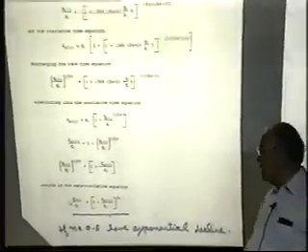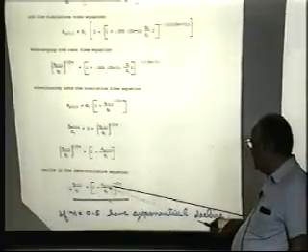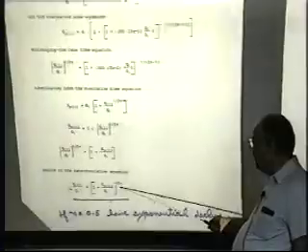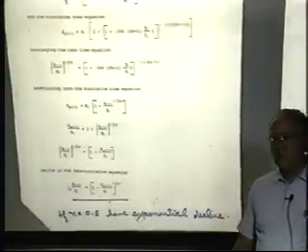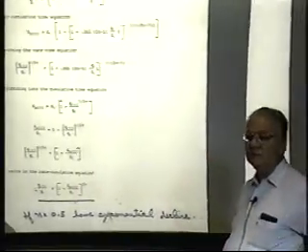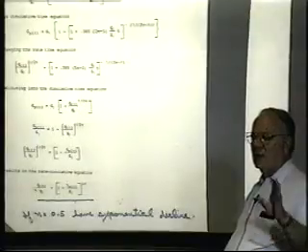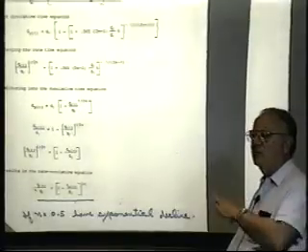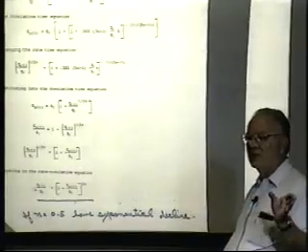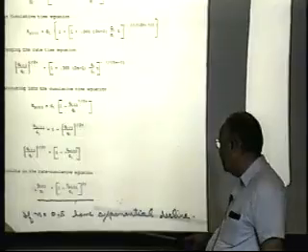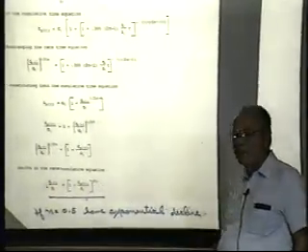The way it's used by the average engineer is you plot it and you get a straight line, and you do an extrapolation. They're making the assumption, well, they don't realize that the slope of the back pressure curve is a half, or it's exponential. So if you're doing a rate-time plot and a cum-time plot, and you're getting different answers, you should be getting the same answer if you're doing it right. One of the problems, again, is people don't realize there's an exponent there and they drop it.